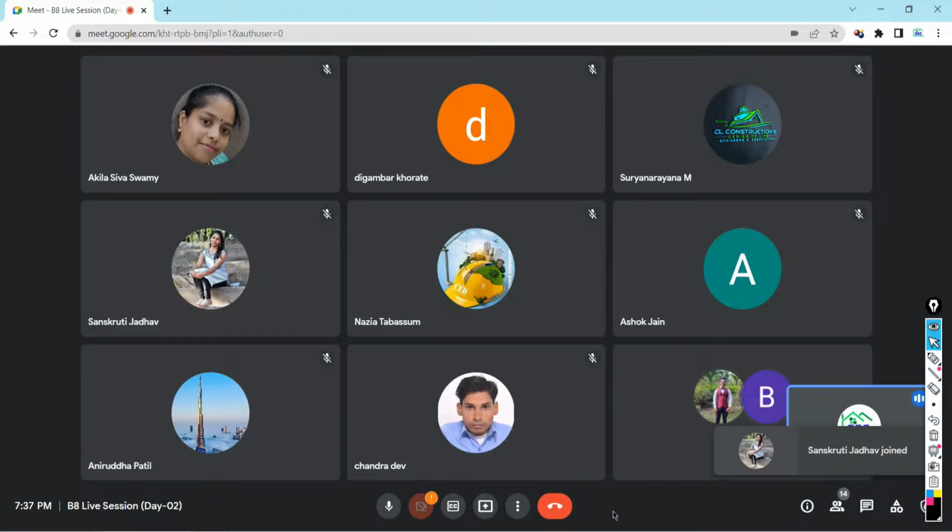Second thing is that we saw the different methods of preparing, creating the grid lines. Without grid lines we can't proceed. The different methods are: first, the offset point method; second, the ETABS quick template option; and third, the export and import method. And in which situation we have to choose any one of these three options, that we have seen. The offset point method is normally not in practice. The last two methods are actually in use, that is the ETABS quick template option and the export and import method.